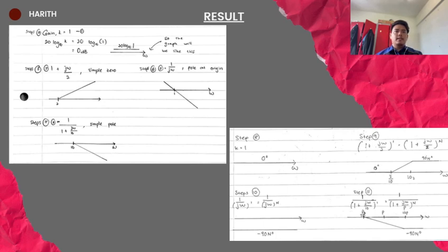For the phase plot, sum the individual phase contributions from all factors, noting where each begins to affect the total phase angle. The contribution of these four factors allows us to model a wide range of system behavior, from simple gain adjustment to complex resonant dynamics. By understanding how each component influences the overall response, we can effectively analyze system stability, design appropriate controllers, and predict performance across the frequency spectrum.